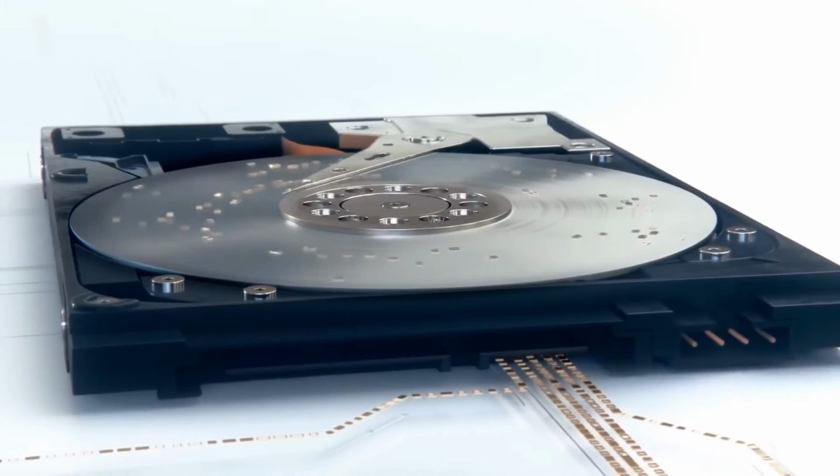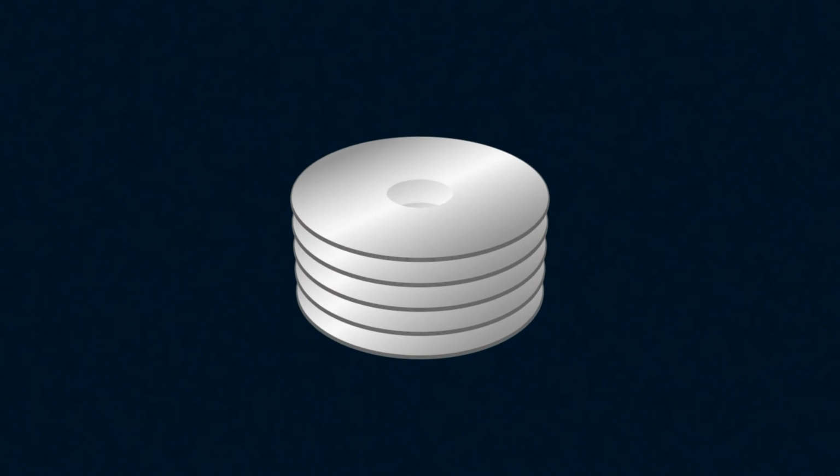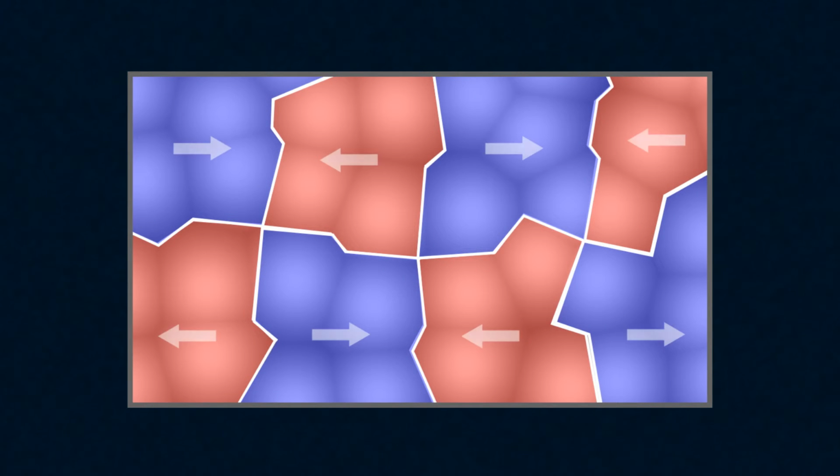On a hard disk drive, information is stored on small circular disks, usually made of a magnesium-aluminum alloy, assembled into small stacks. The surface of each disk is covered with microscopic concentric tracks made of a ferromagnetic material, usually a cobalt, chromium, and tantalum alloy. The tracks are divided into sectors, and each sector is divided into cells, each of which contains one bit of data, i.e., 0 or 1. Data is written by magnetizing cells in one way or another, making each cell a tiny magnet.